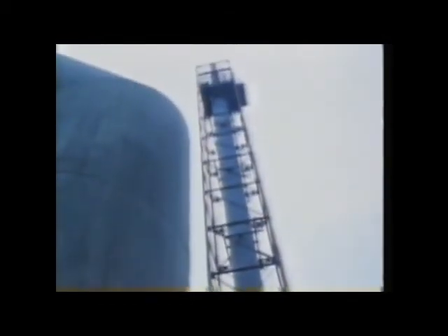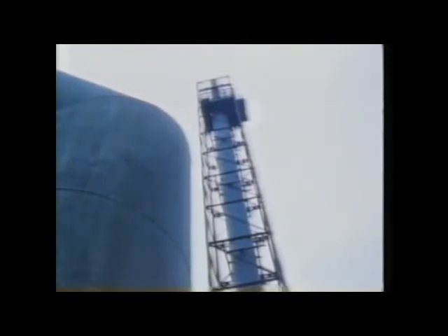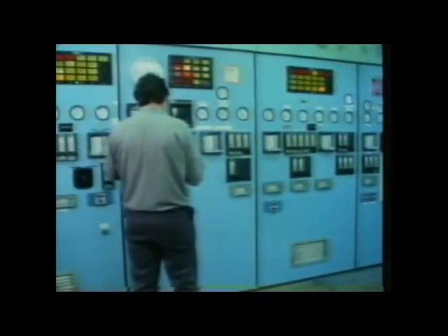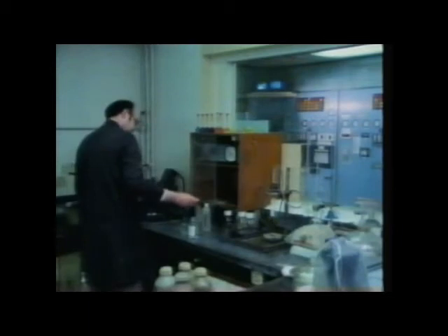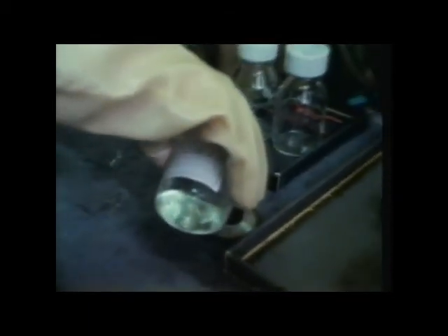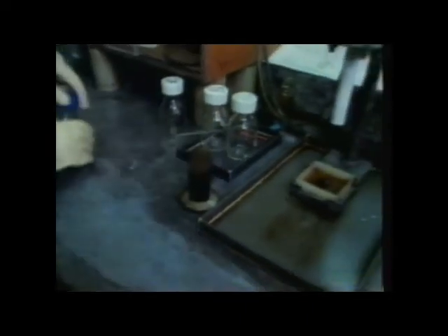The waste gas emerging from the sulfuric acid plant is mainly nitrogen from the air drawn in at the beginning of the process. There are traces of other gases, and these are analysed to make sure that only very tiny amounts of sulfur dioxide get out into the atmosphere. In the control room, the whole process is monitored continually. The plant produces about 33 tons of sulfuric acid an hour, running continuously day and night. Samples of the product are tested. Electrical conductivity measurements show its concentration.